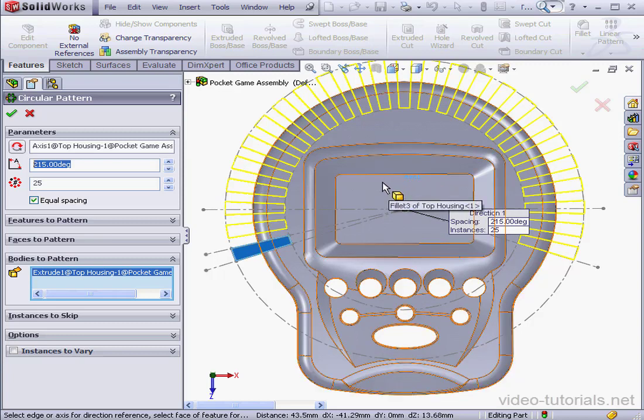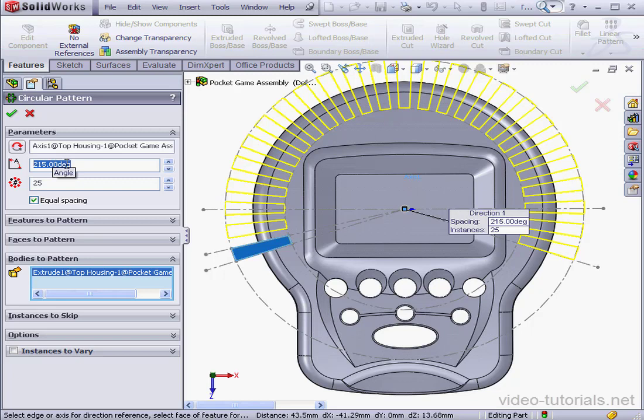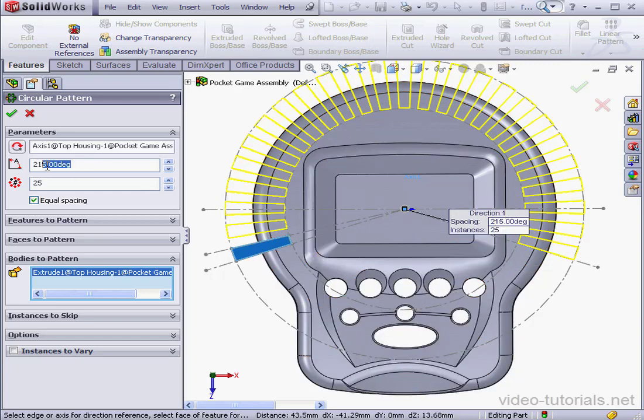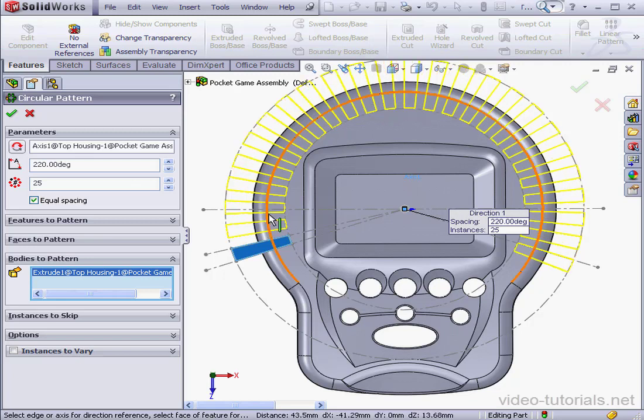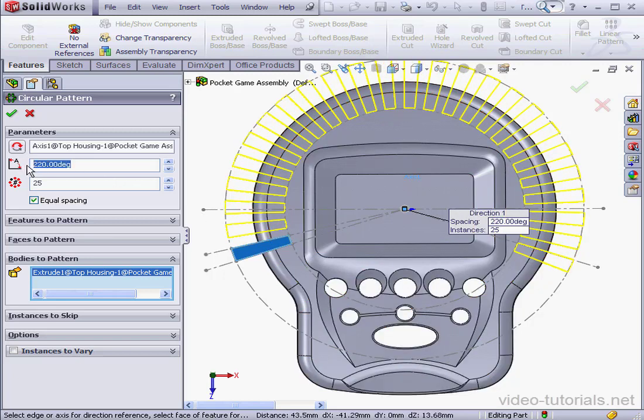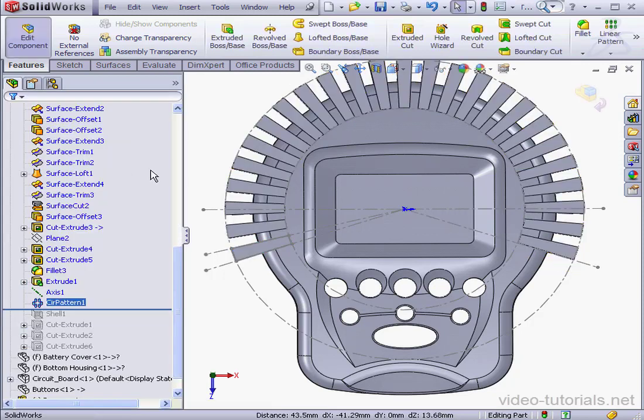So where's that missing 5 degrees? That discrepancy occurs because this segment itself has got a 5-degree resolution, as you may remember when we created the sketch. I've added that here, which makes both sides equal. Let me demonstrate again. If I change this angle to 220, tab to register, now the left and right sides are no longer symmetrical. Let's restore to 215 and click OK.